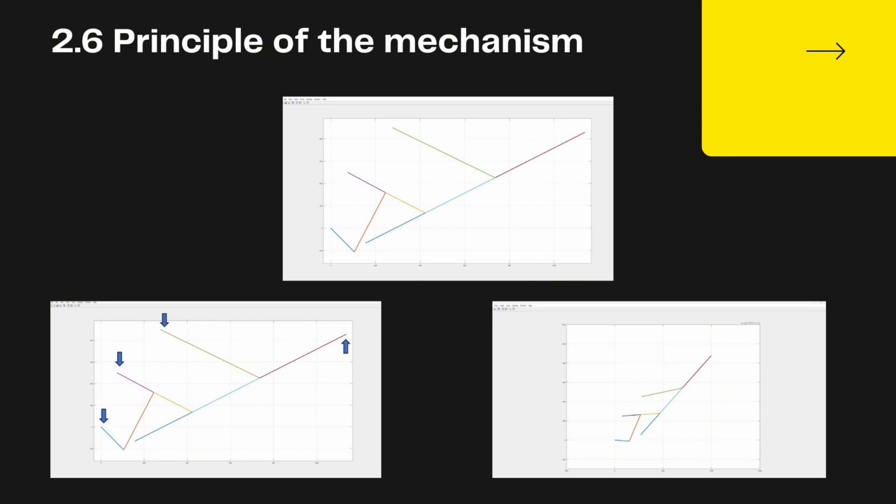This mechanism may involve hydraulic, pneumatic, or electric systems. Hydraulic systems are common and consist of a hydraulic cylinder connected to a pump. When the pump is active, hydraulic fluid is pressurized, causing the cylinder to extend and lift the drum. And the tilting mechanism is responsible for adjusting the orientation of the drum. It allows the operator to tilt the drum to a specific angle or position as needed. This mechanism may also be powered by hydraulic, pneumatic, or electric systems. For example, a hydraulic cylinder can be used to control the tilt angle.